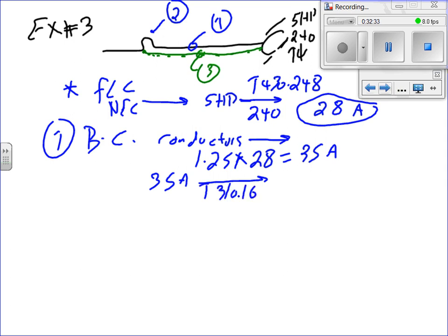310.16, and that will get you a healthy number 8. How many? It's not enough to say number 8. How many? Two, right? Two conductors, number 8 AWG. What insulation? Designers, what insulation? The assumption, if it's inside a dry location, is THHN unless you know otherwise. Everybody knows that? Otherwise, if it's a wet location, you use THW or THHW. Any questions, guys, about that?